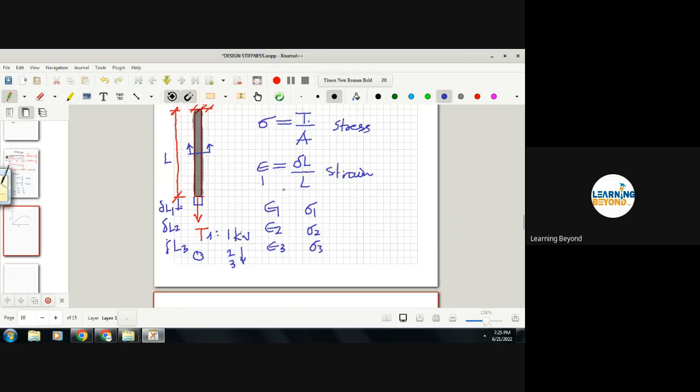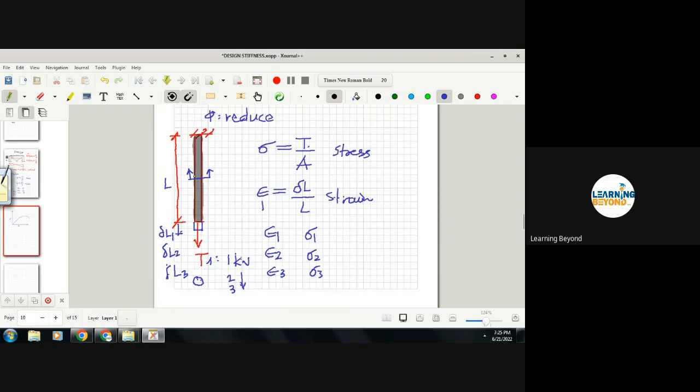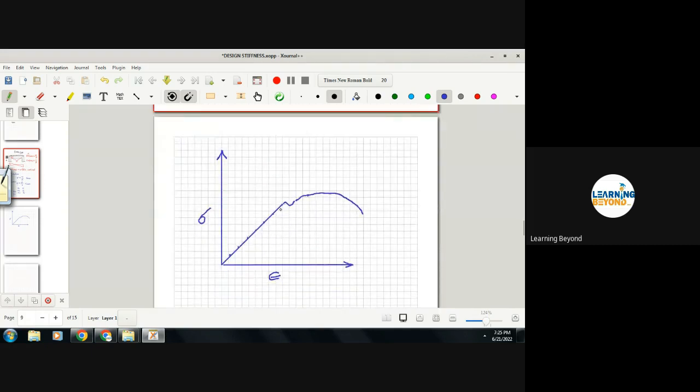So all of you know that whenever the rod elongates after some point, there is a neck formation, the diameter is decreasing, as some of you said. Then after that the diameter is changing very much, or we can say this is a neck formation. So when there is a neck formation, the length will increase very high even though there is a little change in the force. Now you can see this is the point. Till this point the stress and strain relation is linear. So as you increase the force, strain is also increasing linearly.